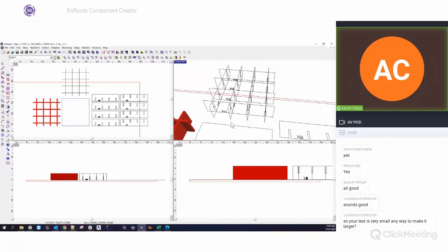And the great thing is here is over to the right, it creates all the pieces that you would need in order to create this piece. So I've got all my parts. Now all I have to do is nest and toolpath these and send them to my router. All 2D cuts. So everything you do in here will create two-dimensional cuts to create a three-dimensional-ish type shape, or a three-dimensional type shelf, or some kind of component. So that's the idea here, is that it is kind of 3D-ish, but it also creates a 2D part so that you can cut it all out very easily.